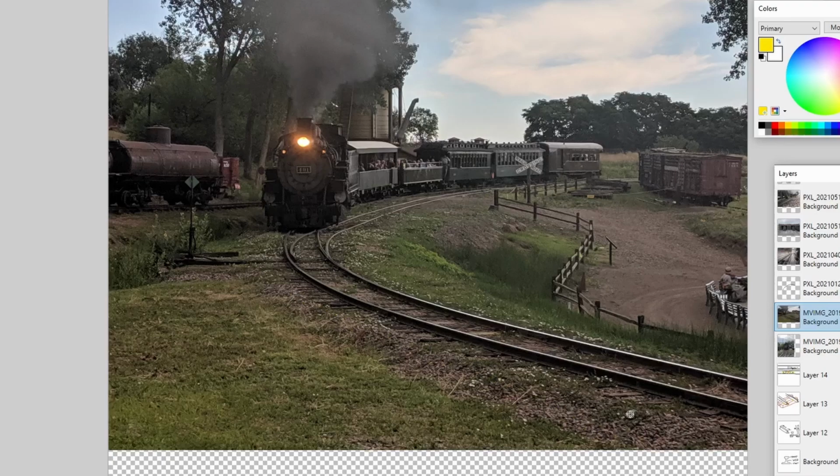Thankfully, proper ballast is very simple. You need crushed rock, is what the people in the rock industry want to call it. Not river rock, not smooth stones. You want jagged, I've been squished by mechanical processes and I've got lots of pointy edges that'll stab you rock. That kind. And you need a lot of it. And it needs to be tamped. And what that means is you basically need to smack the crap out of it so that it settles perfectly, and every little one of those edges is crabbed in on any other piece of ballast all the way up to the ties and all the way around the ties.